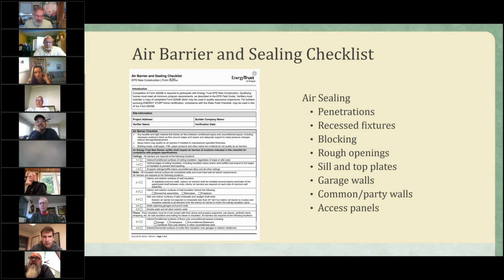Mike, is there a gap between the drywall and the wall? Yeah, it's there, and we found that for $30–40 worth of sill seal, you can do a 1 ACH drop. So as odd as it sounds, yeah, we do see that. It's kind of caught everybody off guard, but we've noticed a big difference in homes when that's done.